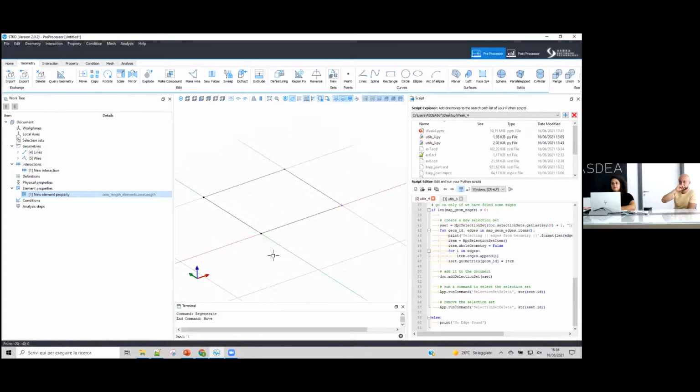Regarding the distribution devices, you need to find the corresponding uniaxial law in OpenSees, and then you draw a zero-length element, and you assign that uniaxial model to the zero-length element.